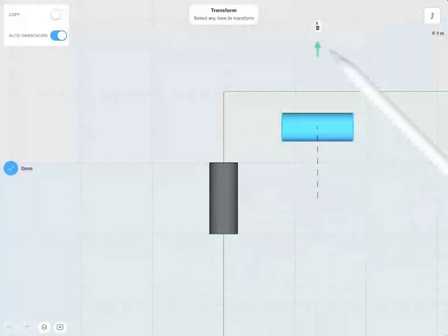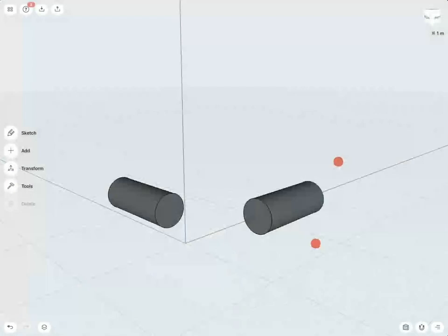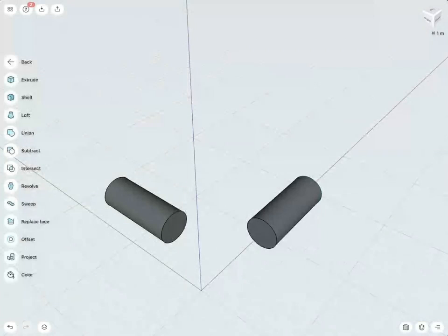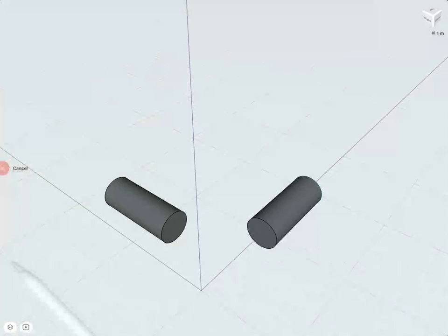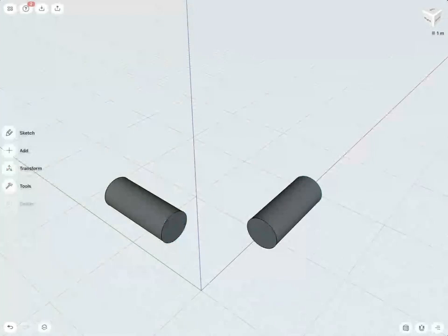And between these two now, I would like to create a nice connection. So I need to reposition these first, and then I need to also be able to create the arc. And essentially, it's just a variation of what we did before. So I will go with project and say this arc and this arc. So these end corners project onto the grid. Very good.